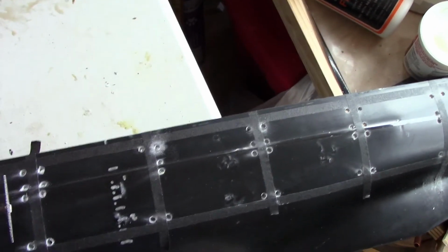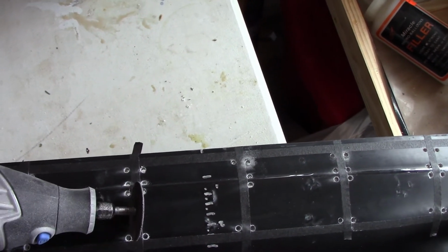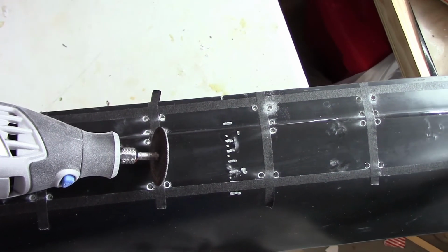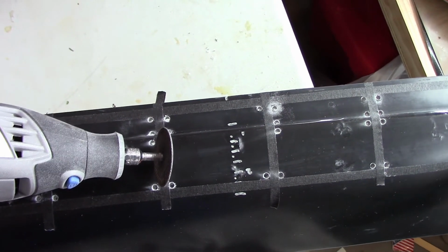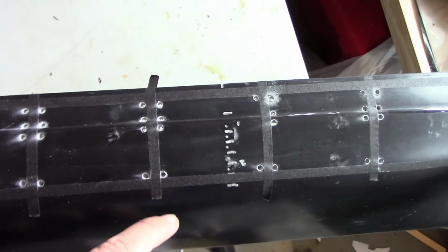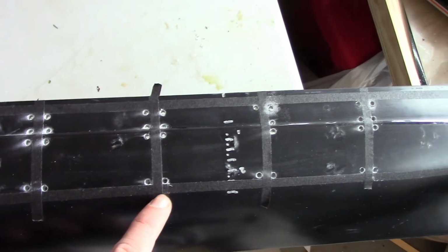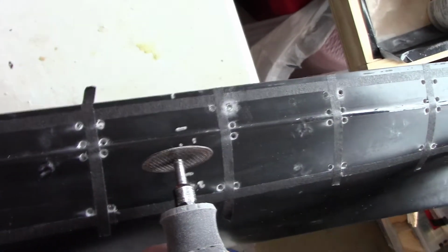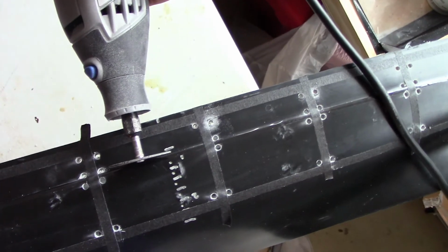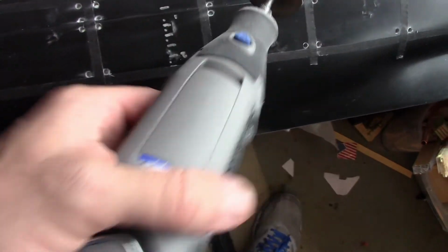Another thing I do is I always try to angle the cut, because the wheel's going to have to go in at an angle for a lot of these spaces, so I'll always angle it away from the edge I'm cutting against. What that does is make the cross section of the ribs more like trapezoids than squares, so they'll be 1/4 inch in the front but wider in the back, and that will make them a little bit stronger. I'll do the same on the stringer here. The bottom cut I'll angle like this, and then the top cut I'll angle like this, and just do that on each edge as I go.